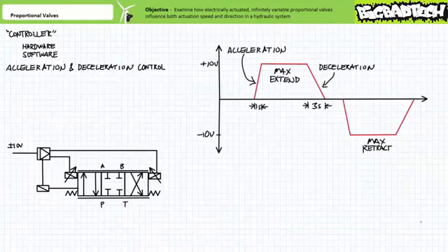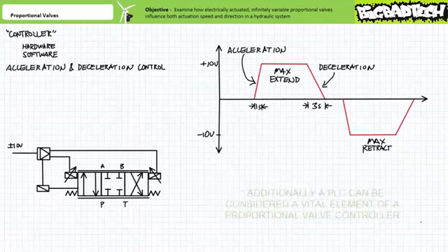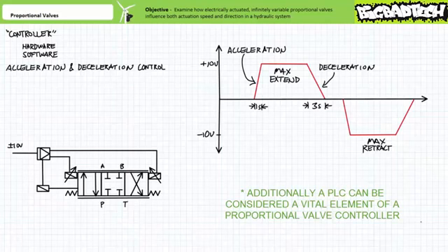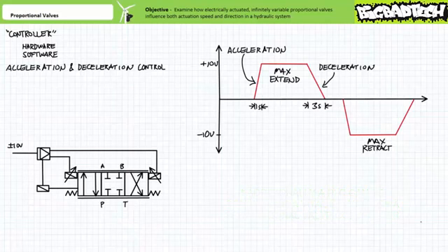Another example being a PC running manufacturer-specific proprietary software used to program a proportional valve. When the program is stored in the proportional valve's non-volatile, meaning semi-permanent memory, it's disconnected. Like I said, what truly constitutes a proportional valve controller and where this boundary ends and begins is like nailing jello to a tree. For now, let's just assume it's a conceptual box that includes some pretty cool functions, only one of which I'll introduce now: acceleration and deceleration control.